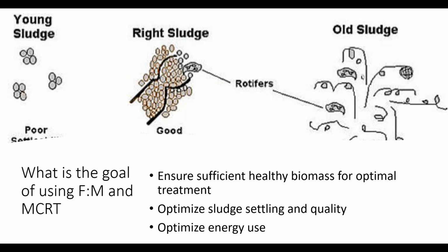If you have unnecessary return activated sludge pumping or unnecessary oxygen pumping, those are all things that would unnecessarily consume energy.